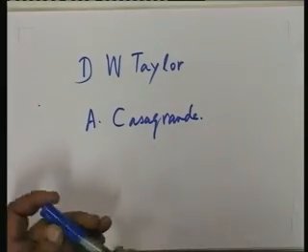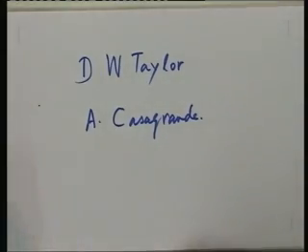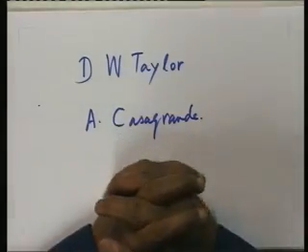What is special about these two methods is they are both curve fitting methods. That is, we get an experimental curve of compression versus time, and we do some curve fitting on these in order to get certain data on the basis of which we can compute the value of CV.